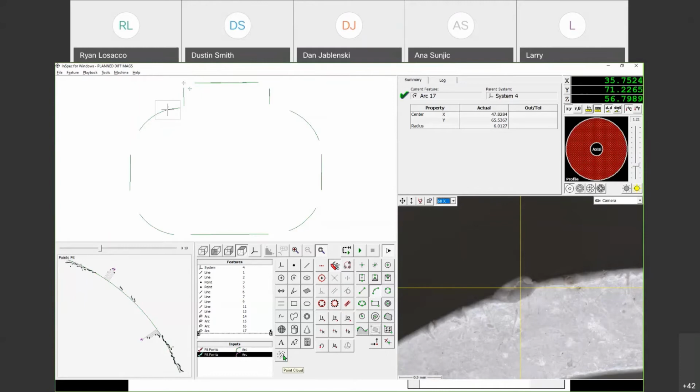Getting any raw data, measuring any lines or radiuses, anything like that, it's really nice to use a point cloud because you can pull data out of that point cloud and use it for multiple different things. In the program that I'll show here in a little bit, it was measuring this line down an edge, and they were looking for the farthest point in negative X from the datum structure, and they were taking multiple best edge points down the edge of it.